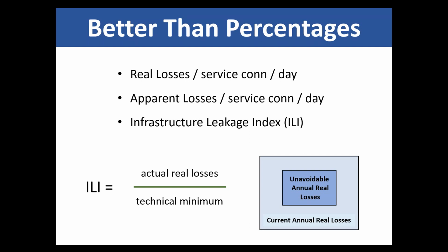I mean, you all know when you lay a new pipe, right? The pressure test, you have some leakage allowance already there. So that's part of our infrastructure. There will always be leakage, and we try to acknowledge that to say, here are the minimum allowances in leakage for any given system, and that's driven by miles of mains, number of service connections. And then realizing, okay, well, this is where we theoretically could be.